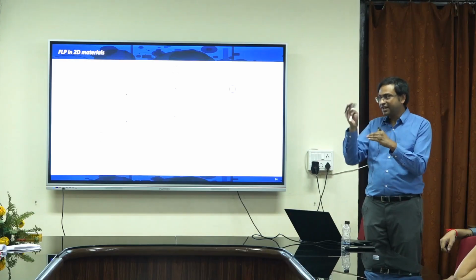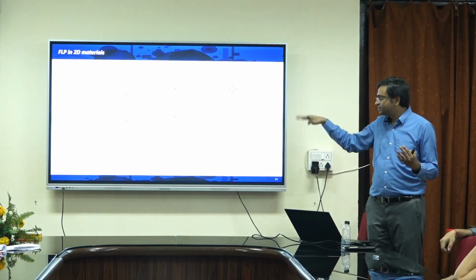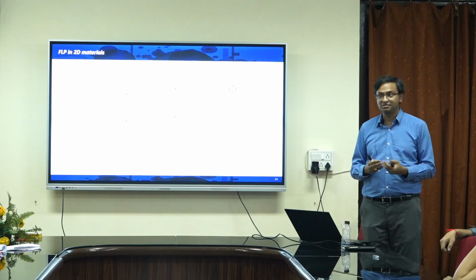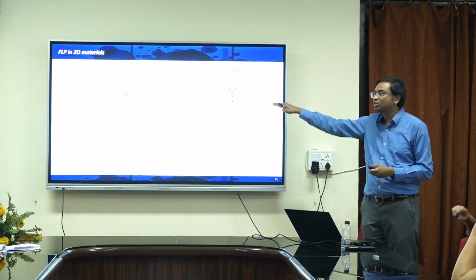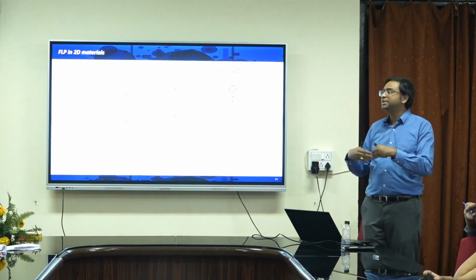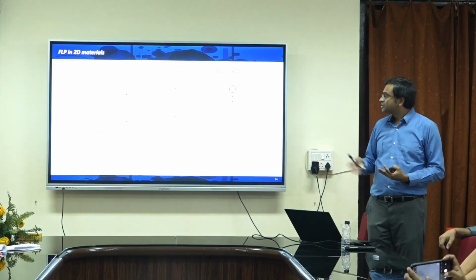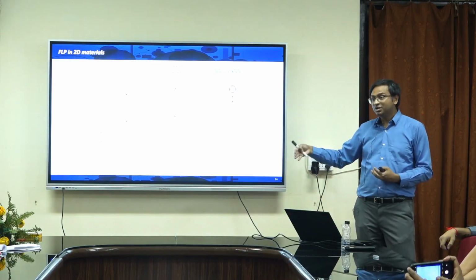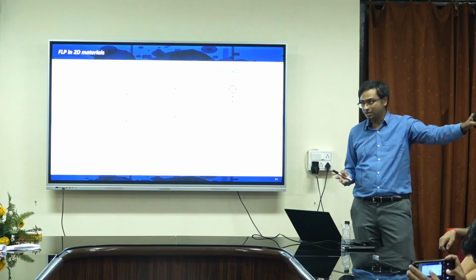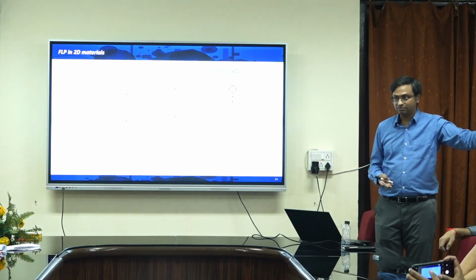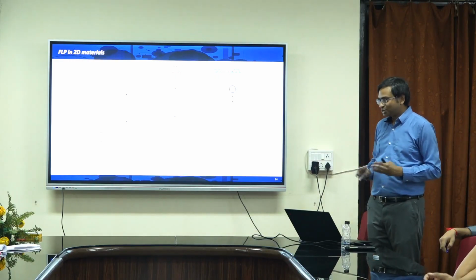So you get a little bit N, a little bit P, and it becomes ambipolar. But both branches are pretty low in current because they are going through a Schottky barrier. Better for black phosphorus, but in black phosphorus the pinning is closer to the valence band. So you can get an easy P FET, but you cannot get a nice N FET. So this is another level of problem with 2D materials, this Fermi level pinning, which defies our textbook understanding. Therefore it becomes even more severe, because ultimately we have to make an ohmic contact.